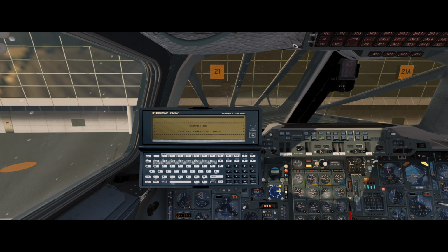There are over 106 different scheduled and non-scheduled engineering test runs that you can pick from this device, and it's generated by FS Labs themselves. You can also put in your own user-generated flight plans and it will attempt to calculate the necessary stuff. Okay, so as you can see, we have a call sign, our departure runway, our arrival runway, our alternate of Gatwick. Your departure gate is 21, arrival gate will be 421, and this is the rest of the stuff. Zero fuel weight of 87.8 and a takeoff weight of 173.6 today.